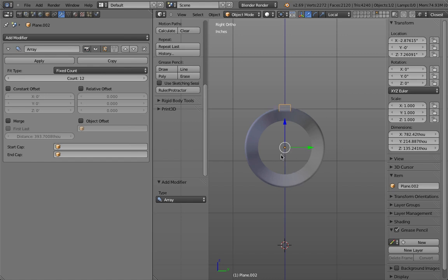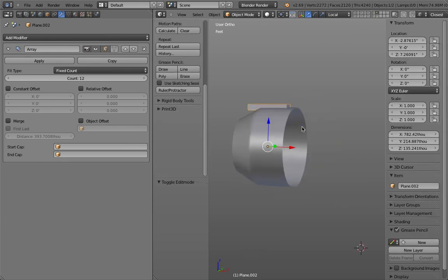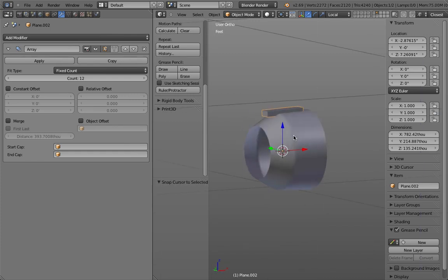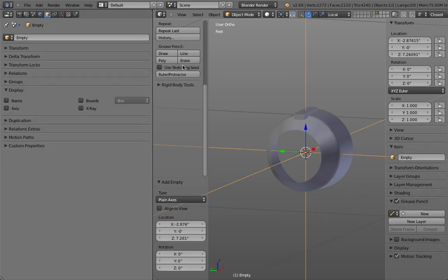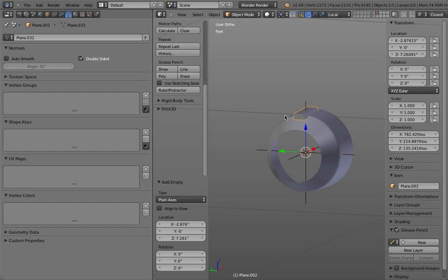We want this to rotate around a certain point. So this means the object center has to be the center this one will rotate around. So the mesh has to be away from the object center. Where the object center is, I press Shift S to place my insert marker, and then I place an empty. I do not scale the empty, but I just by hand inside the empty property change the size maybe to 1 inch.